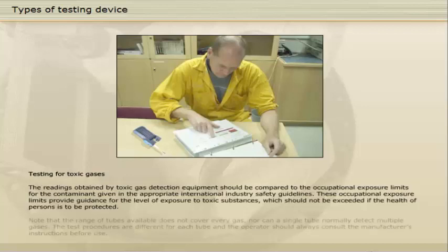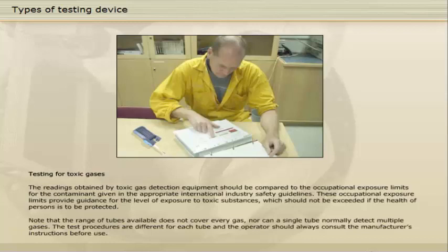Note that the range of tubes available does not cover every gas, nor can a single tube normally detect multiple gases. The test procedures are different for each tube, and the operator should always consult the manufacturer's instructions before use.